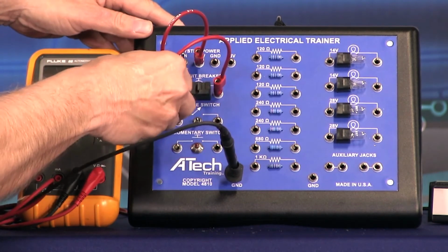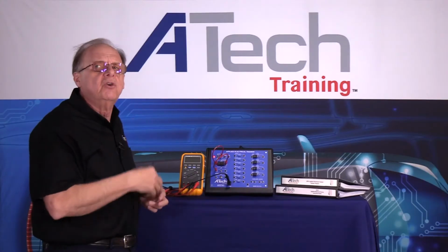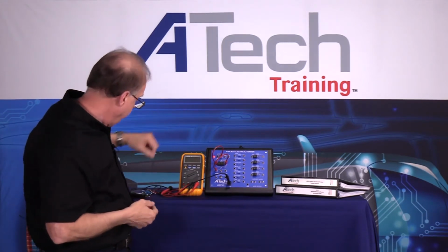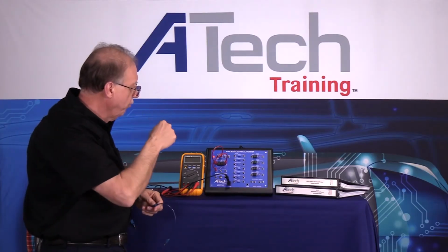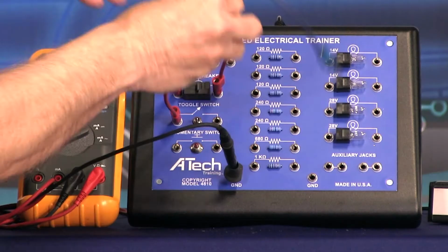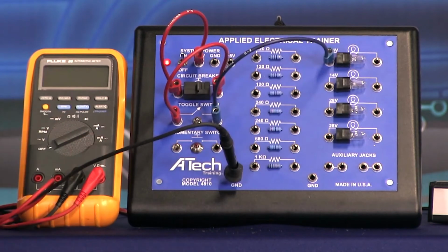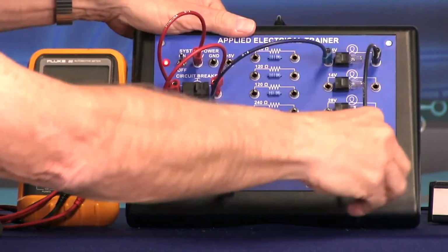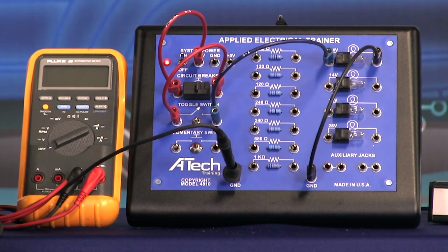And from my circuit breaker I'm going to feed into my switch, which, if you were looking at the wiring diagram, you have to find where the switch is fed from. Again, you can associate this with a different circuit and apply it through. So I have my feed. I'm building the feed in the circuit right now. I want to feed from my switch over to my load, so I'm going to go from here to here. Now to complete the circuit, I have to have some kind of ground. I've already talked about the ground, so here's the deal: we're just going to take the black lead and put it to ground. All right, that completes it. That's a simple series circuit.